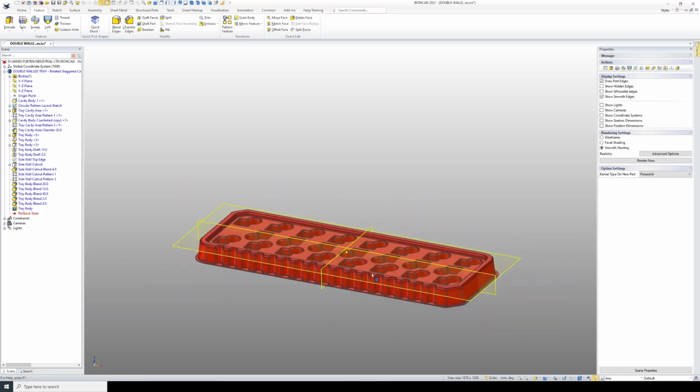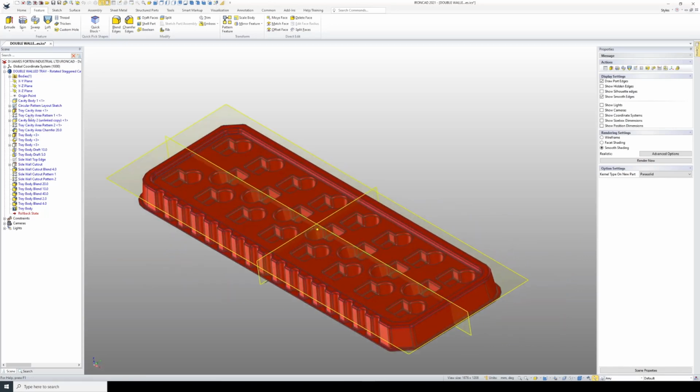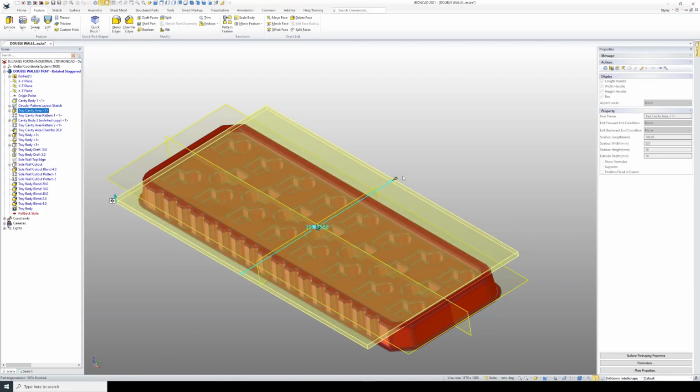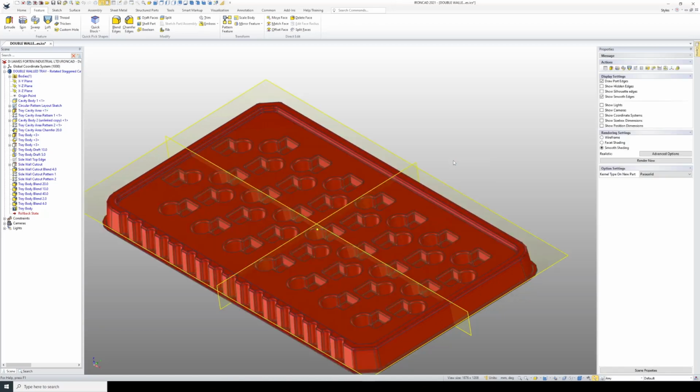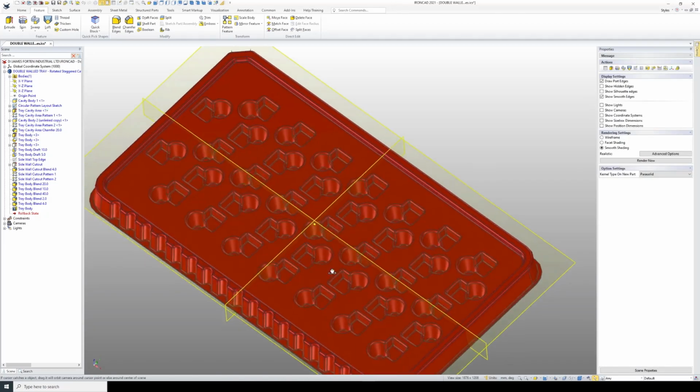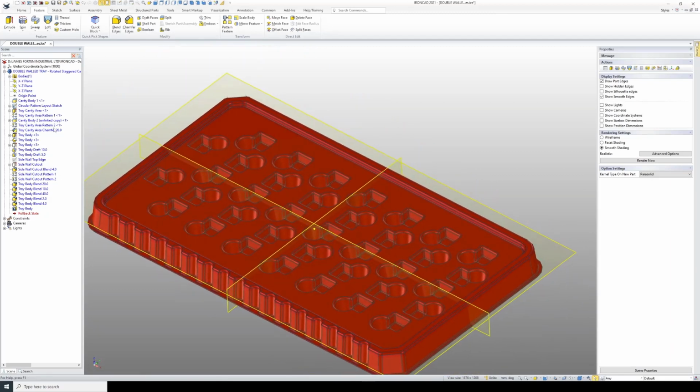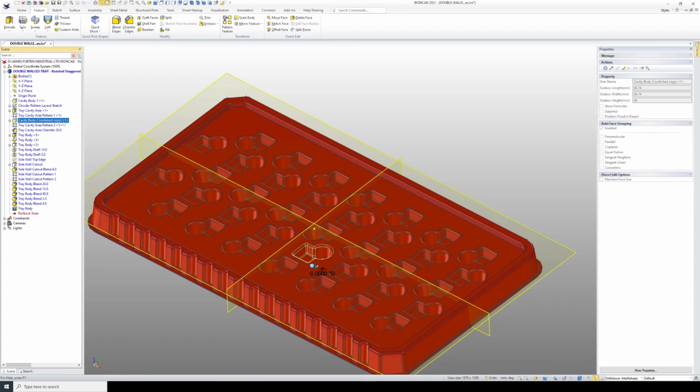Right, new tray, same again. Tray cavity area, we'll change it out this way. I can set a value, but we'll just accept that. And IronCAD's going to calculate the rest. So there we have it, our rotated, staggered cavities using unlinked copies.